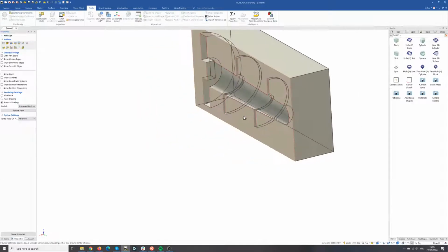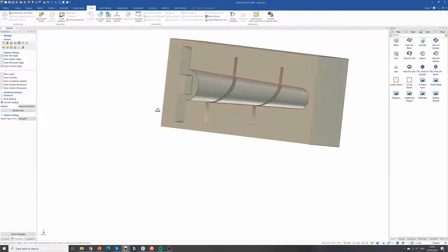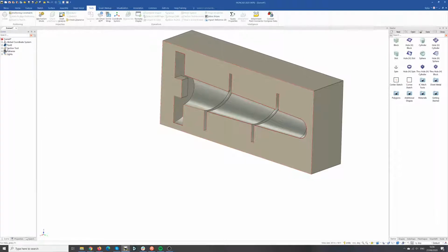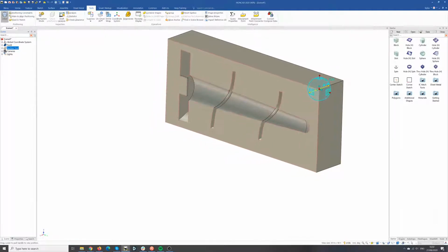and there you cut all the way through, and you can see, let's turn off the hidden edges, and so that's a section through. That is not what you're after, Keith. I'm just showing you that we've taken the one part away from the other part. What you need to do now is split it. This is just a visualization, which if you wanted to, you could actually go in and select that part, put on the triad, and actually move that, and you can see that it moves all the way through.